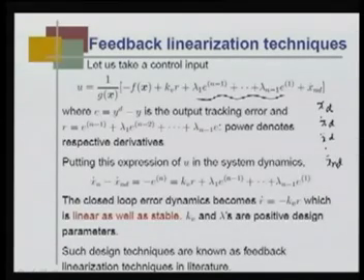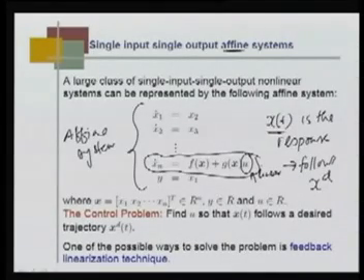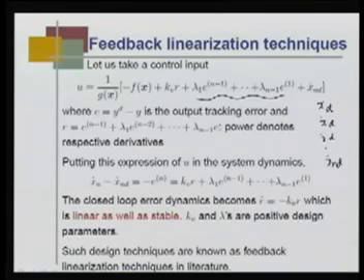So, if I place this u here, so I bring the control law that I proposed and put it here and simplify this expression, I get x_n dot on the right hand side, and the left hand side is x_n^d dot. I bring it to this side as minus x_n^d dot, which is obviously minus the nth derivative of e, the nth derivative of the tracking error, equal to.